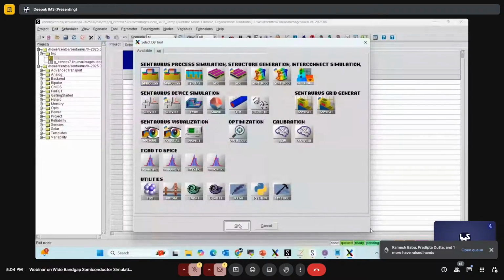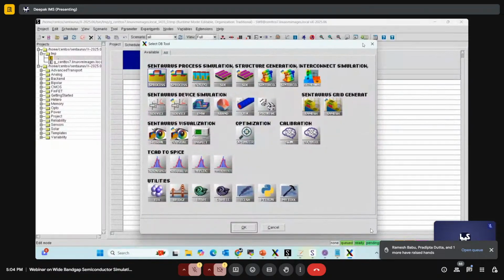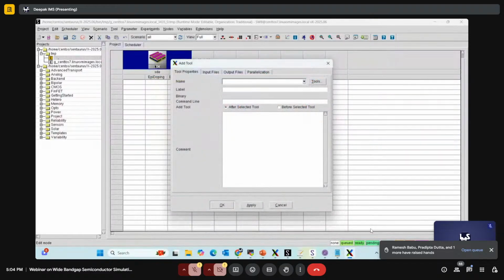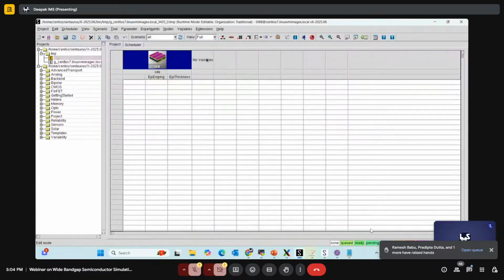Sir, if you are going to create any kind of device, then I think you know their functions, their materials, their exact coordinate points. Only then can you create a structure by using the layout builder. And once you are done with the layout builder, then you can integrate. Integration is very similar. You can go with the structure editor here, and at the right side you can add the process simulator this way.